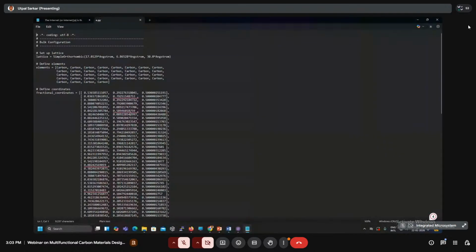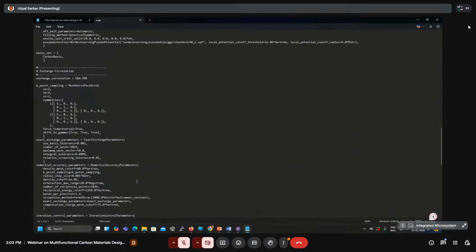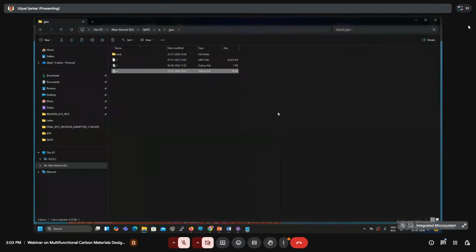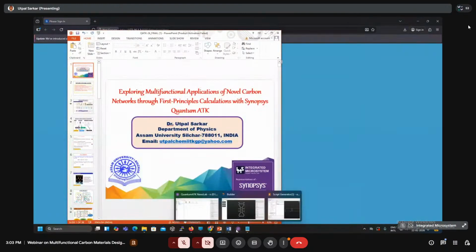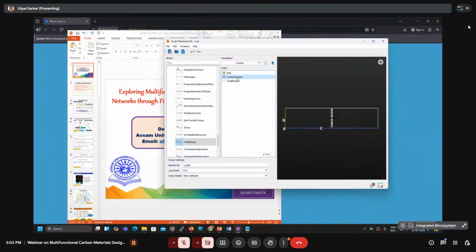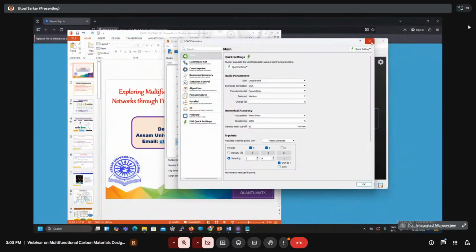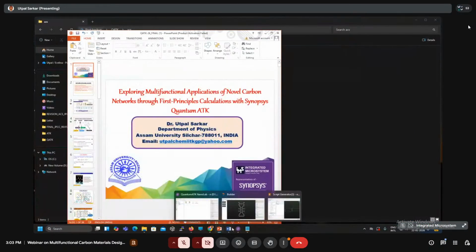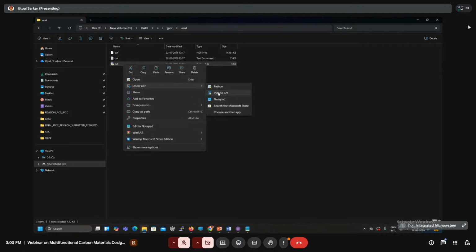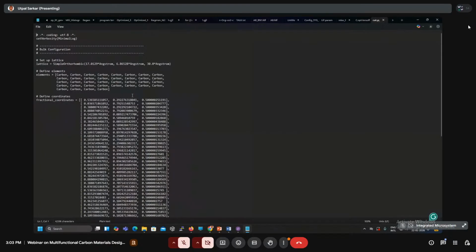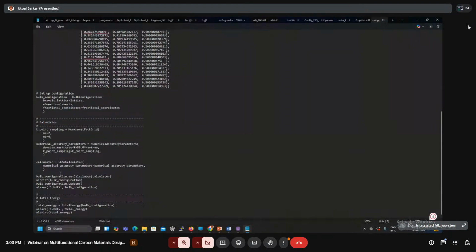Here this is the e.py. You can see this is the py file that has been saved for the energy convergence criteria. Now you can go for the simulation, and you can monitor the total energy in the log file. I am showing you the log file also, how the total energy will be printed. I have taken an already simulated geometry for your convenience. Yes, you can see this is the log file.